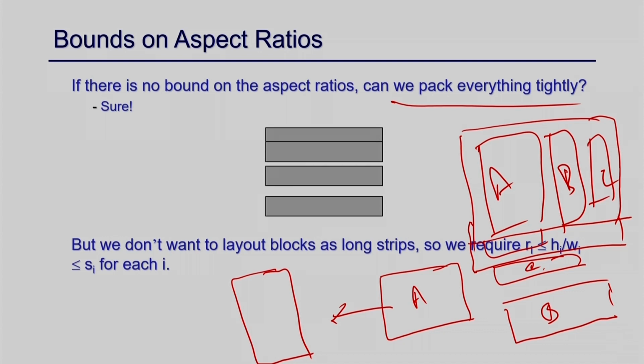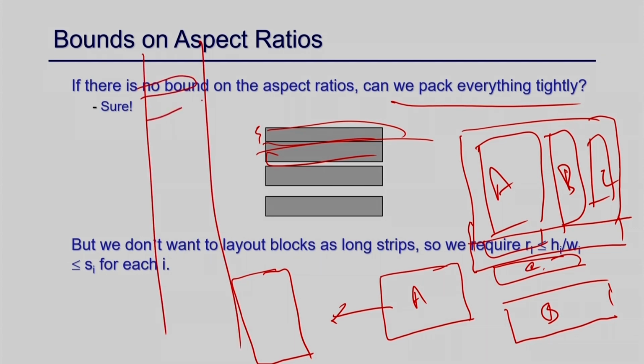One might think, I just make the width 1 and the length long like this, right. Then the problem is that your chip will be just a series of blocks, which is basically just length, and that is not feasible, right. Your layout cannot be just a long strip, which is not allowed. So, that is why we have some bound on the aspect ratio, okay.